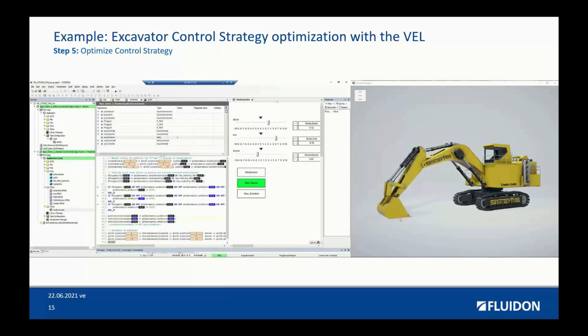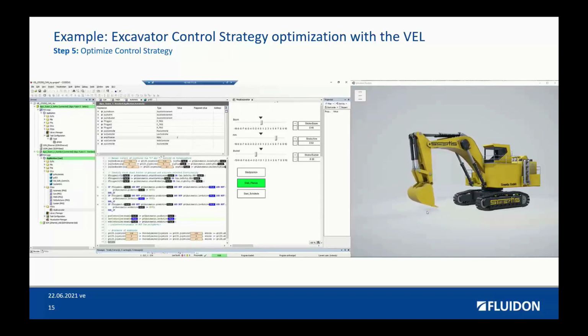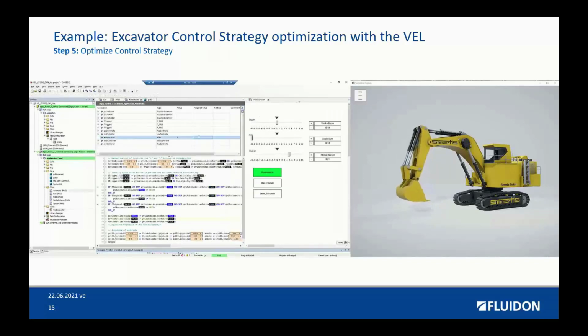What we see is that it's, let's say, digging too deep. It's not scratching on the surface. It's just diving in too deeply. And we see that now the bucket lifts up and even opens, so it's still not the right behavior that we expect. So let's tune it further. I change this amplification factor to 1. In the meantime, I go back to the start position.